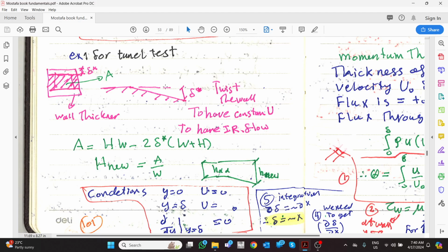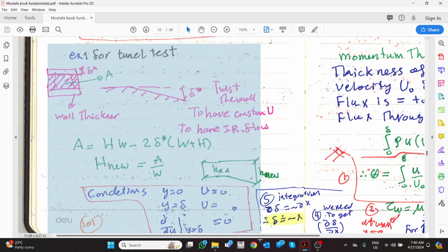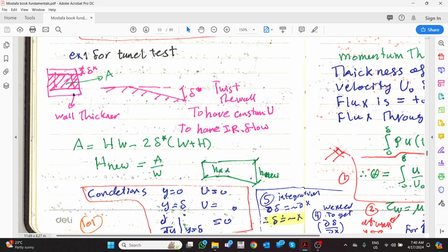Yani, we do it in the wind tunnels, because the wind tunnel is a confined space, and we are doing scaling of the model itself. But if you're going to do a CFD with an actual size, you can neglect this by taking a big enough environment, okay? But it needs to be known because when you're doing CFD and somebody comes to you and gives you a report from a wind tunnel, you need to understand what the condition is. Has he done something wrong or not?